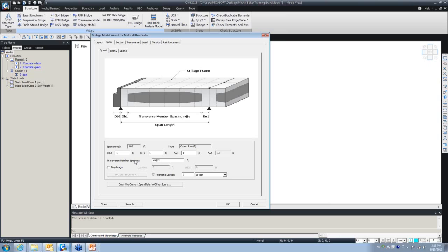You remember we are talking about the grillage method. In the grillage method, we have the longitudinal elements and then the transverse. How often, or what the spacing will be between the elements, is completely in your hands and depends on the geometry that you have.